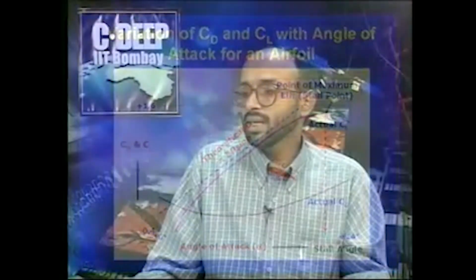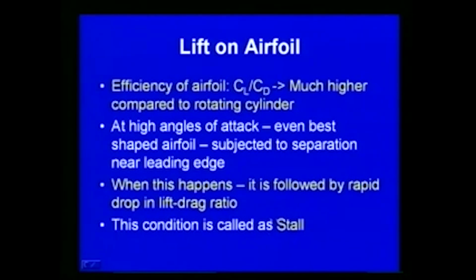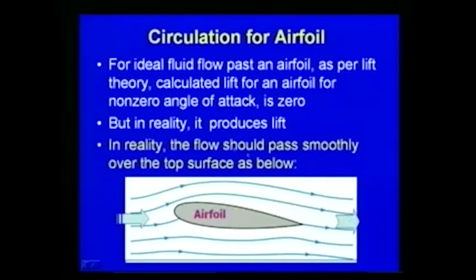Here you can see that as we keep on increasing the angle of attack, initially the coefficient of lift is increasing, and then it reaches a maximum point, and after this there is a sudden drop in the coefficient of lift. This condition is called stall, where the rapid drop in lift drag ratio takes place.